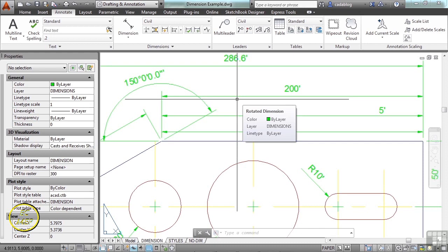It does several things for you. Most importantly, it measures the true distance that's involved, and it means that you can make one dimension style for the entire file regardless of the scales used. Before we had the setting of 2, we just had 0 and 1. We had to make tons of styles, one for each scale that we could possibly use in our drawing. This got redundant and difficult to manage.